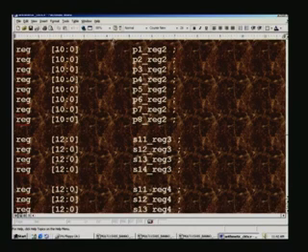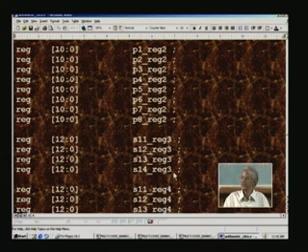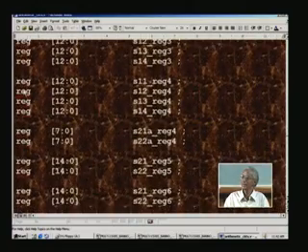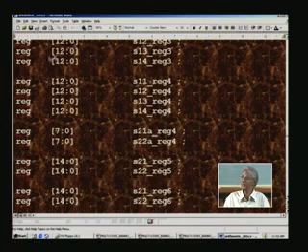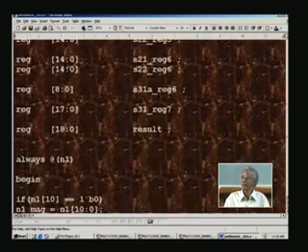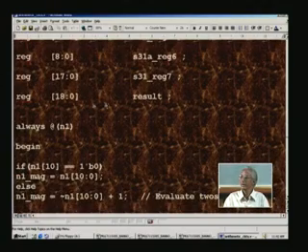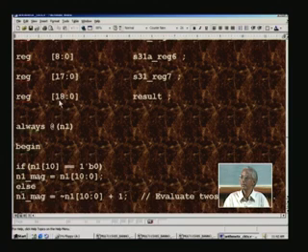So this far I think we had gone last time, and these are all for subsequent stages, say reg 2, then reg 3, all on clock 2 and 3, and all of which naturally would be registers, because we use them in an always block. To start with, the final result will be in 19 bits, and the last bit will be the sign. And here we have a combinational circuit to start with.